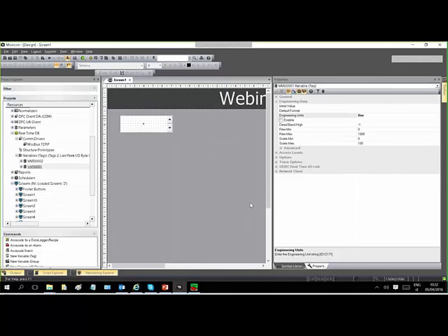You could define and enable a scaling in the variable, because often you are getting from the PLC not a scaled value but a raw value. So you can define here the raw scaling and the engineering unit scaling. You can play on this stuff here directly on the variables. Remember, the multi-selection is always available to speed up. Or you can use another resource of the project that is called normalizer. In the normalizer, you can define your scaling, and you can associate here two variables, the raw variable and the scaled variable, defining here all the properties, the band, and also a non-linear scaling in case you need.